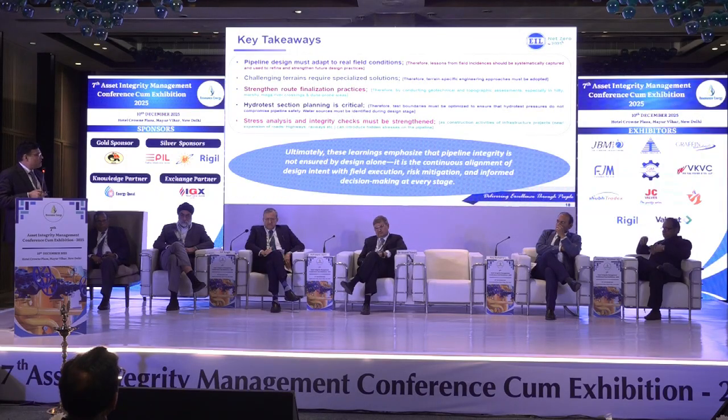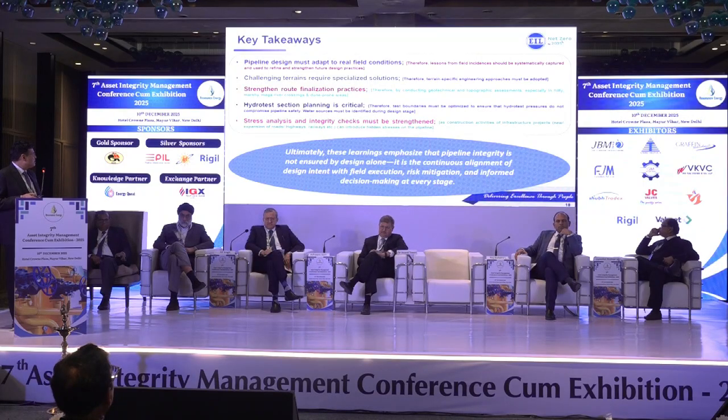So the key takeaways of the pipeline: pipeline design must adapt to the real field conditions. Challenging terrains require specialized solutions. Strengthen route finalization practices. Hydrotest section planning is very critical in pipeline design itself. Stress analysis and integrity checks must be strengthened.